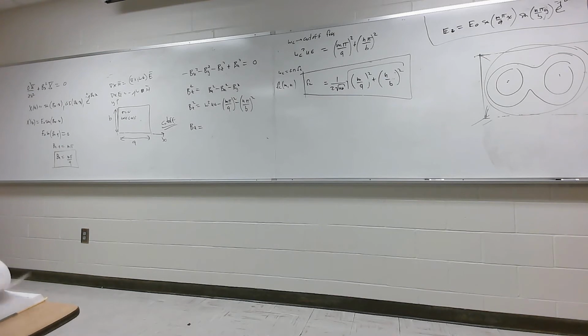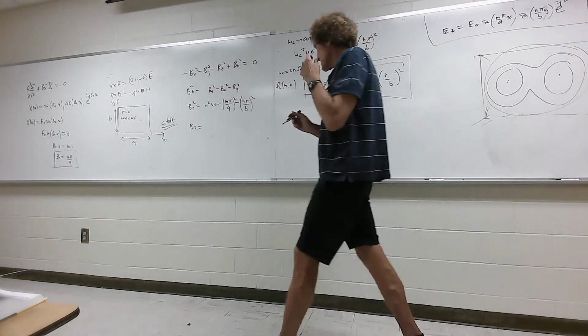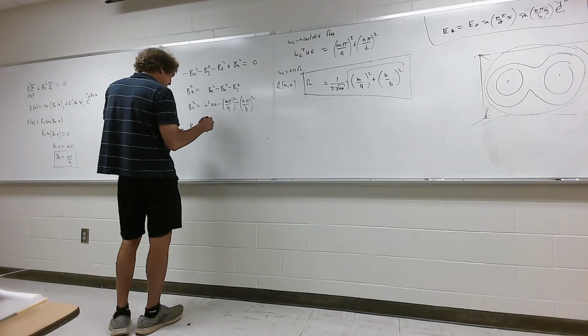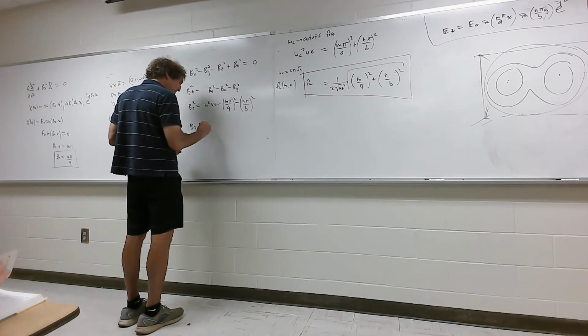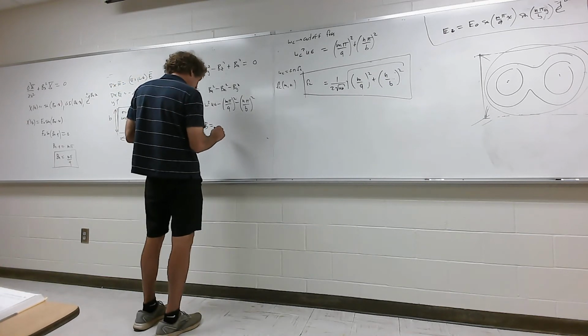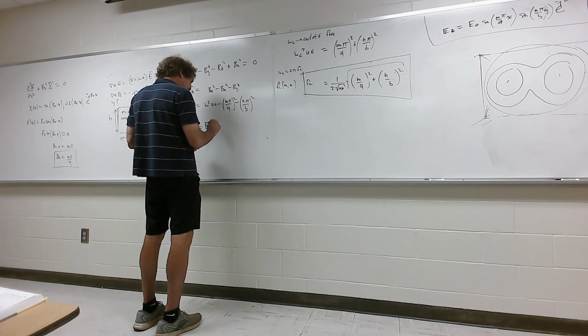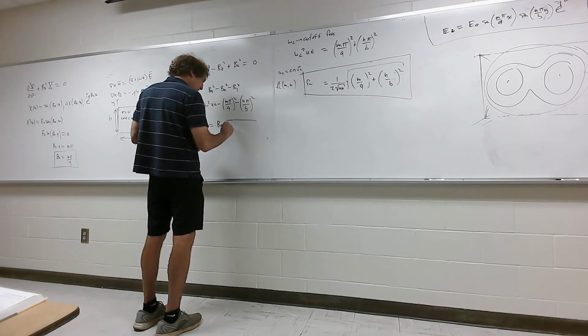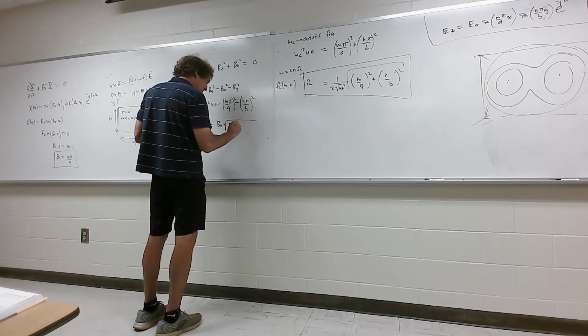And then if you look at page 380, equation 7.11, star that equation. That's your go-to equation. You're going to see beta Z, which Dr. Whitworth's book just calls beta, equal to beta unguided, times the square root of 1 minus FC over F squared.